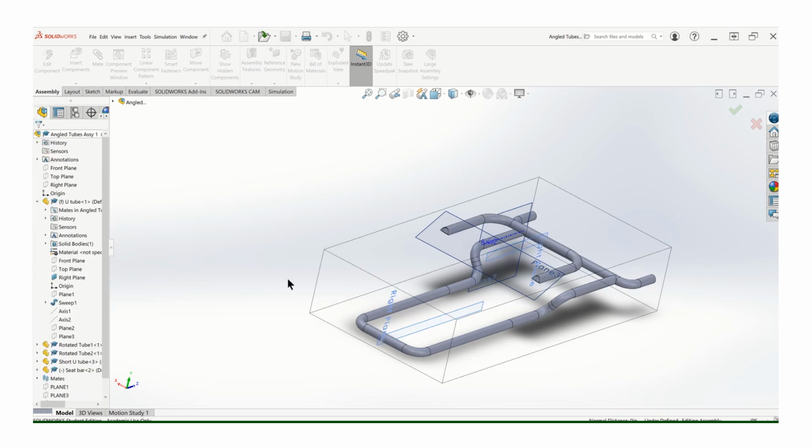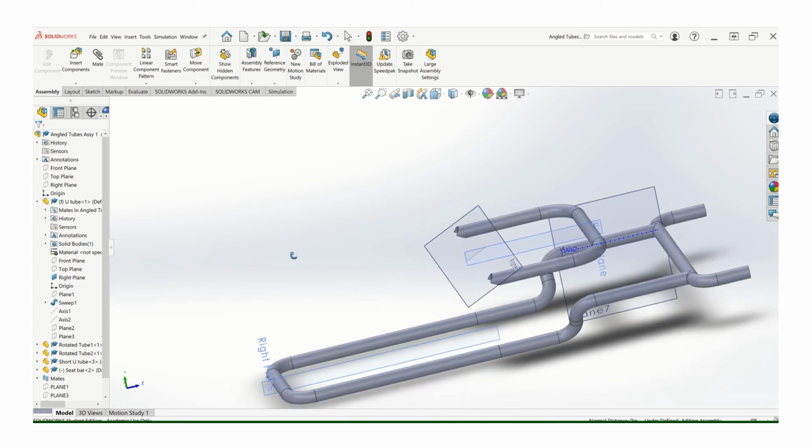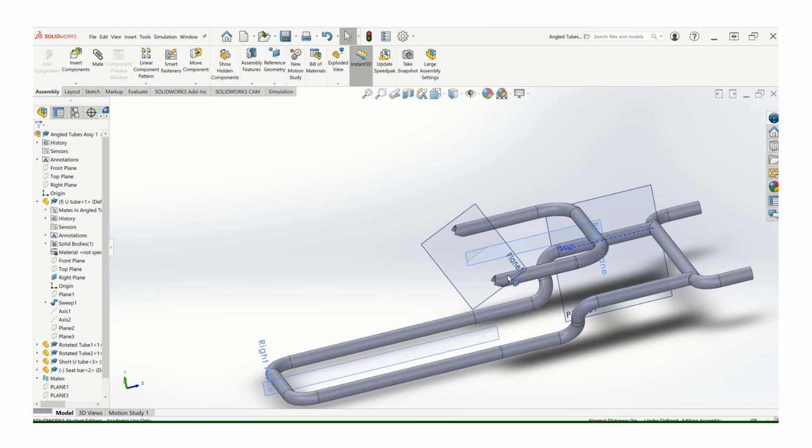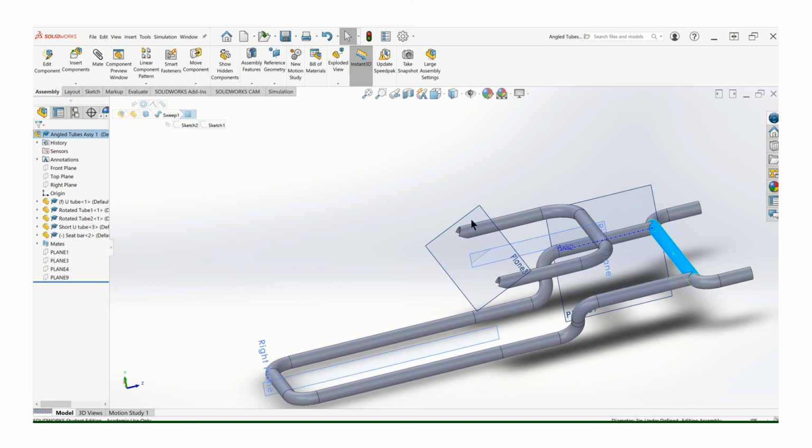Now, if you try to mate with the spacing here, if you try to mate both like that surface to that one and that to that, you're probably going to get an error. If everything isn't perfect to the 9th decimal place, that's why it's really smart to use your mid planes. The other thing I need is a plane somewhere to locate that. I've got it centrally located, but what about side to side? So let's put a plane on here, and I'll probably work off of this tube. These are all going to very shortly become very interconnected because of the way you've got them mated.